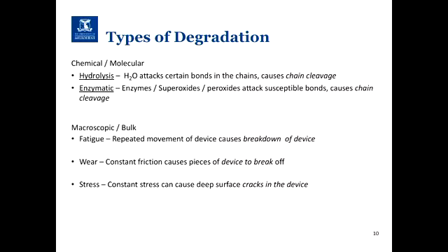So you implant a material into the body. Some materials you want to degrade and some of them you don't. So it can degrade chemically, and that's what I'm going to focus on. But you can also degrade macroscopically, so that's fatigue. So something like a heart valve that has a lot of mechanical repetition, it could degrade that way. Fatigue, you could get wear. So quite often with some of the old hip implants, you get wear between the different components and it starts to degrade, stuff comes off.